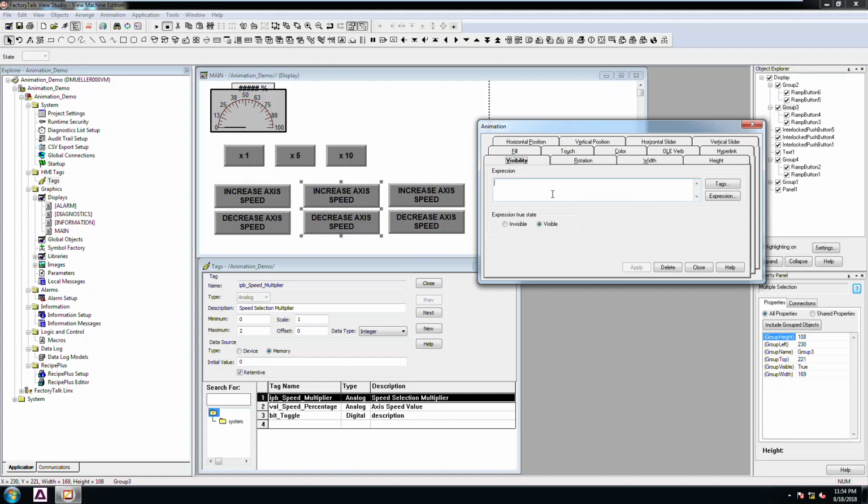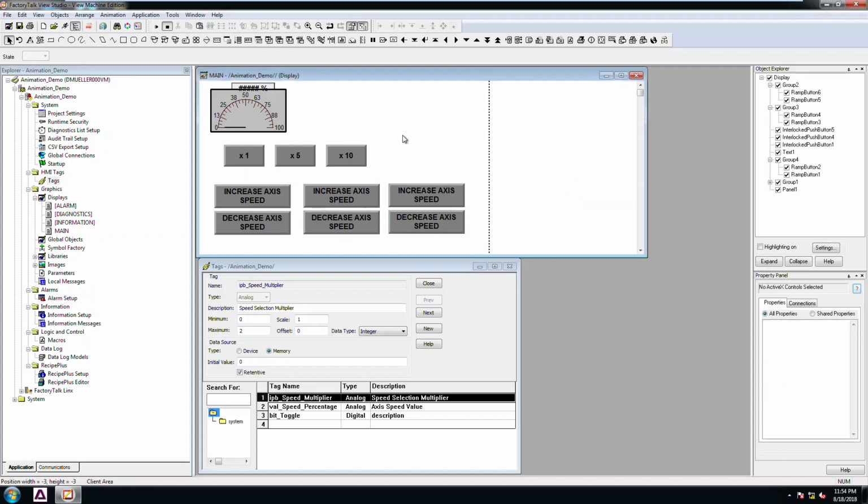So now if you select in here, I don't actually have to hit expression again. I can just paste that in there, and you have the complete control to actually type right out in here if you wanted to. We'll change that to 1 because when it's equal to 1, I want this to add 5. So let's hit apply on that. We'll go to the next one. We'll do the same thing, make that 2, and now that'll make it equal to 2, or the buttons that add 10. So now let's just close the animation window out.